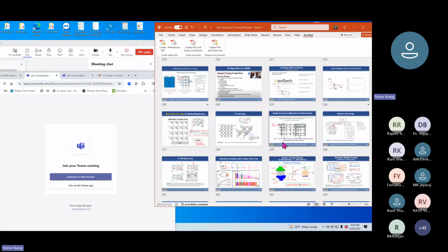So the switch itself will have a drain-to-source resistance, right? In order to have stable, reliable operation, your memristance value should be much higher than those parasitic resistances. The interconnect parasitic is always challenging, so you have to overcome that.